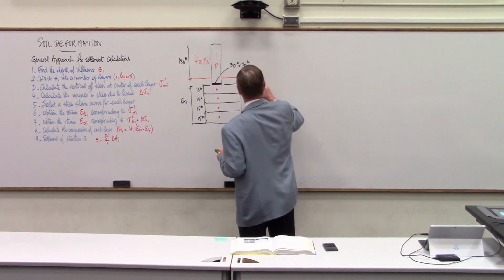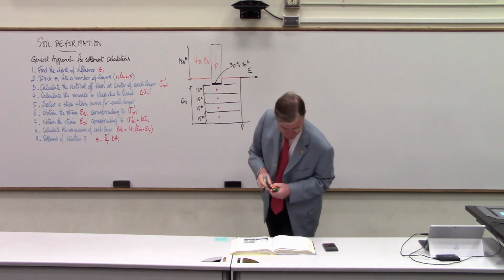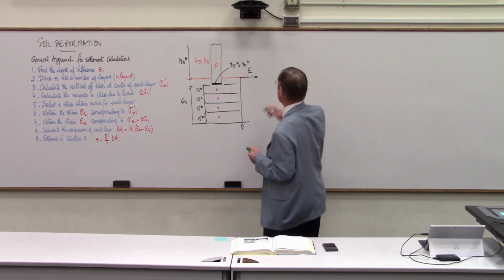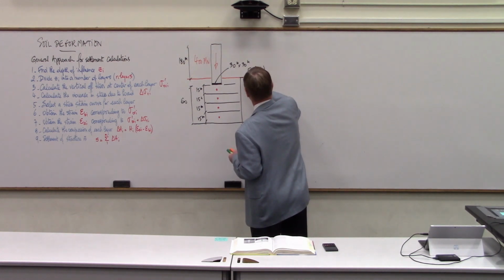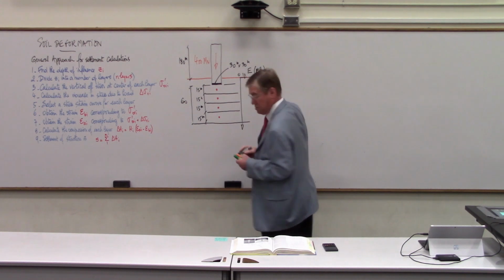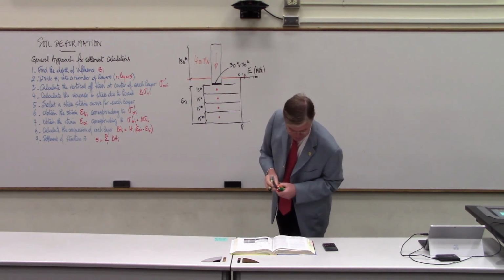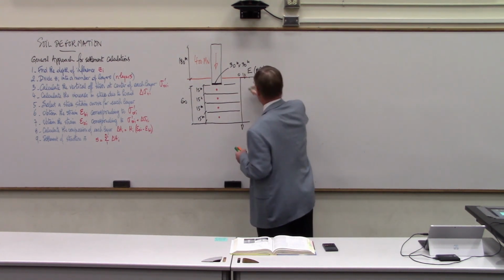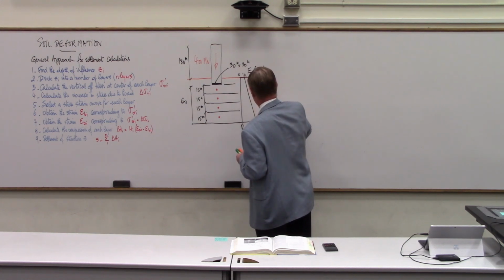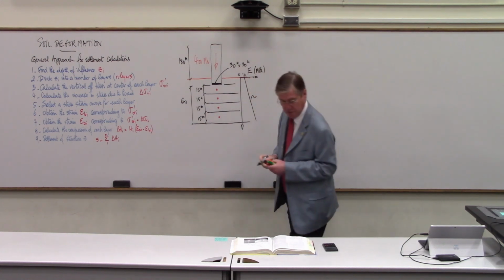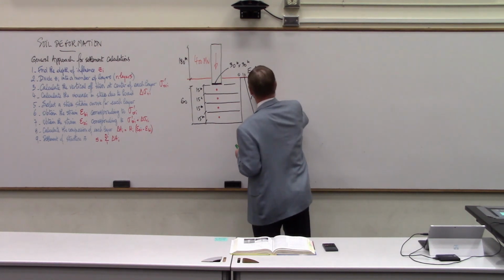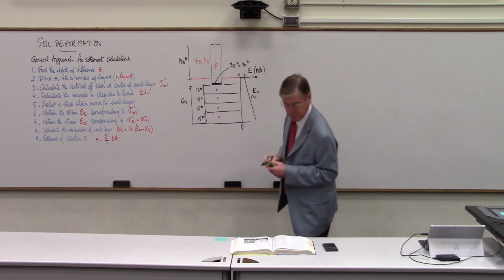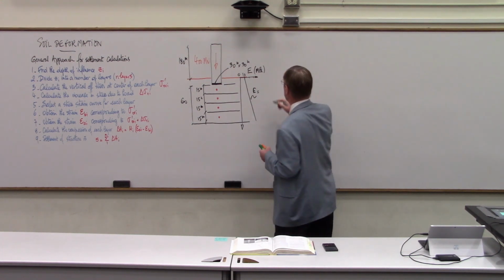So it's going to be E, and the profile starts at 10 megapascal, so we have megapascal here. We start at a value of 10, 20, 30, and so on, and it increases with depth at a rate governed by an equation which says E equals 10 plus 0.5 Z.